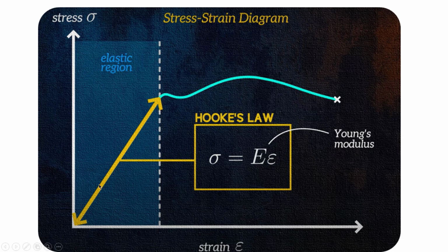If you consider steel, brass or copper, and run the analysis, the stress values will be equal for all, but the strain will change. Sorry, the deformation will change.